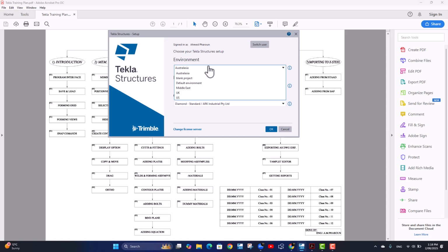The English, or the UK, write the profiles in a different way, same as we do here in Australia, actually. They use UB, which means universal beam, and UC, universal column, and usually they write the dimensions of the profile. For example, UB 275 times 73. You'll find 3 or 4 numbers for the dimensions of the profile.